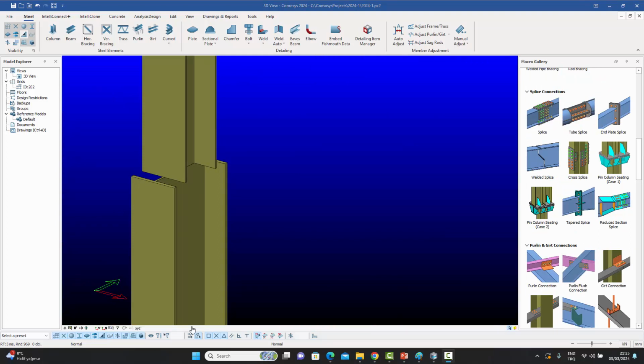Another situation which is very common in steel detailing is when you have a column which is larger in size, and at the next story level or whatever level you decide to have the splice, the column which is continuing is of a smaller size, and not just slightly smaller, but significantly smaller. That really makes using the classical splices, where you can use a few filler plates of maybe a few millimeters thickness to cover for the changing height, very difficult, because the change in the size of the two sections is significant, and other methods can be used to connect.